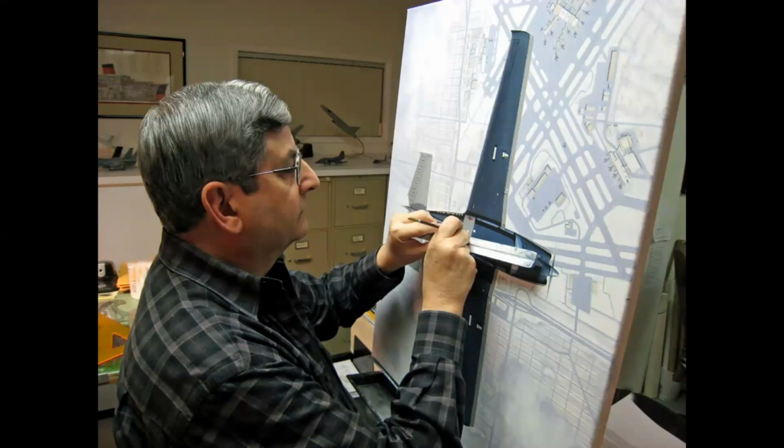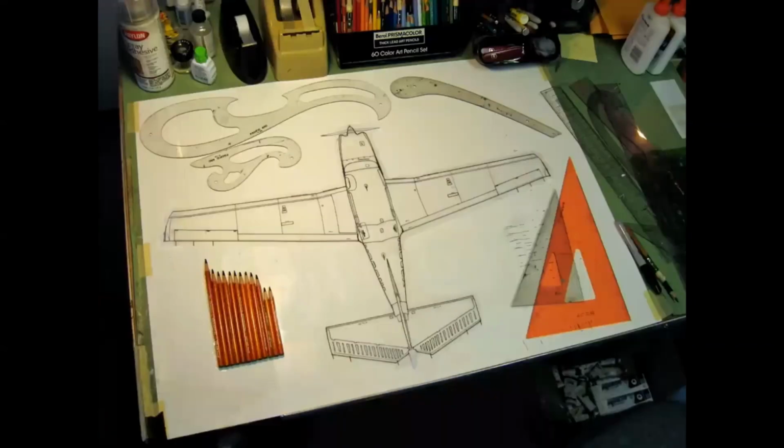Compasses, dividers, and pens provide better results with less annoyance if they are correctly shaped and sharpened and are not damaged by careless handling. Store drawing instruments in a place where they are not likely to be damaged by contact with other tools or equipment. Protect compass and divider points by inserting them into a piece of soft rubber or similar material. Never store ink pens without first cleaning and drying them thoroughly.